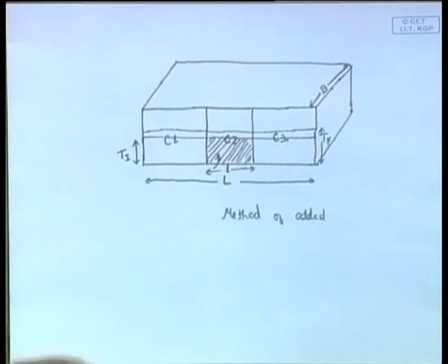So it is like this in the method of lost buoyancy, but in the method of added weight what happens is that we assume the ship is there, buoyancy is still the same, but new weight is added. It is the same concept again. You are doing the same thing, in one place you are adding, in one place you are subtracting, but it is still the same process. So instead of assuming that the buoyancy is lost, buoyancy is the same, but weight is added. Because of it new weight has come, buoyancy is not able to balance it, so the ship has to come down. The process is the same, you will get the same draft.